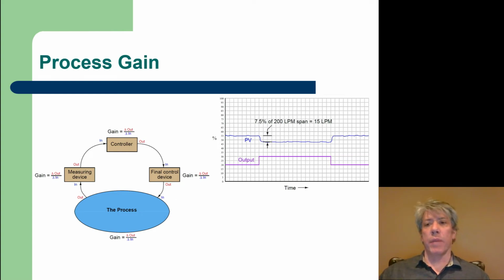Now, if you think about the parallel form of the equation, where we have Kp, Ki, and Kd as the process gains, if you want to change the gain of the controller overall, you have to change all three of those gains. But in the Honeywell form, or the ISA form, I think it's called, you've got the proportional gain multiplied by a quantity that includes the error, the integral of error, and the derivative of error, with some TI and TD tuning parameters. And when you change Kp, the gain, you're changing the overall gain of the controller. And so that's why that controller equation, the Honeywell form, is preferred, because you can easily change the gain of the controller by just changing one number without having to retune your controller.